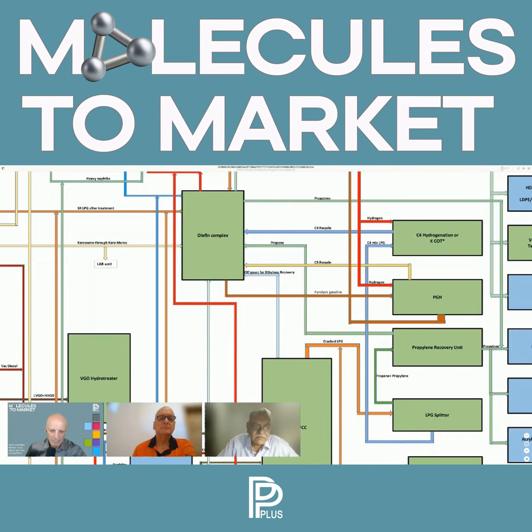And your intention of doing the FEED is that you come to a level of detailing so that you can have an accuracy level of estimate of plus or minus 10%. So in certain cases, on the strength of the FEED document, one can commit to firm costs and also go to the banks if required to seek loans or support.